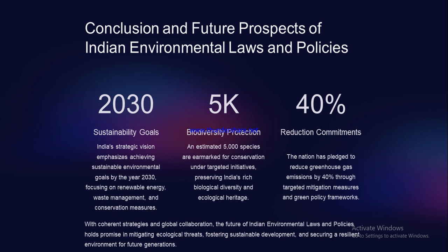There were very important provisions of this particular act, which was passed in 1974. So there was establishment of a board, formation of state and central pollution control boards was enforced. Regulation of pollutant discharge into the water bodies: industries were required to obtain consent before they discharge any kind of effluent. Water quality standards were set up, and in this context, the drinking water standard IS 10500/2012 was formulated. Then there were penalties for